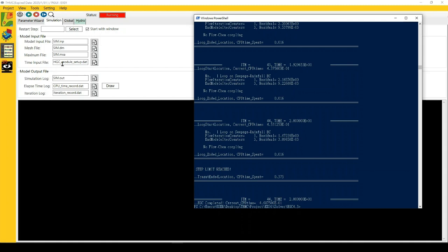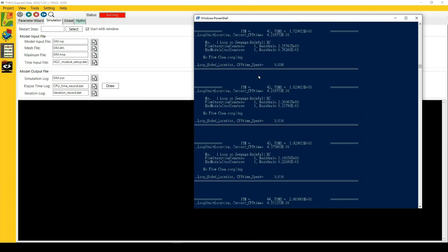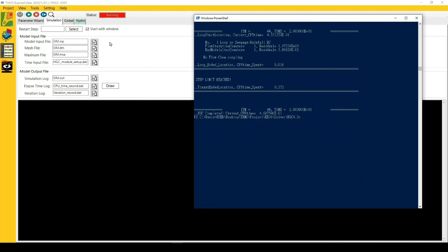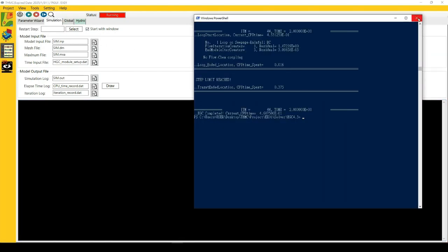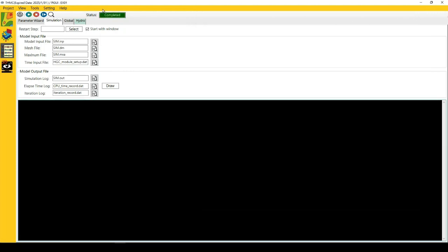And you can check the last message of the log window and the last message of the simulation log as the first step when debugging. You can also turn on the advanced mode by clicking Advanced in the View menu bar. Thus the simulation will stop in PowerShell without closing. Then you can see the error message or manually start the model execution in PowerShell.